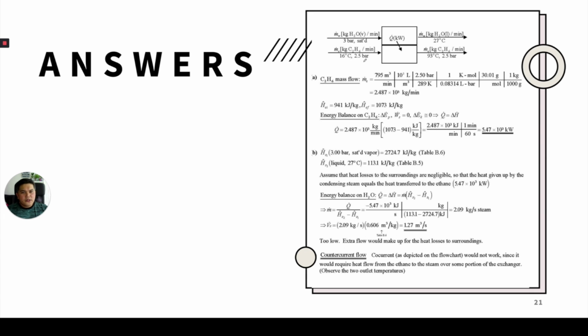So let's look at the solutions, right? So when we have actually the heat exchanger, okay, what I'm trying to do is trying to label this in a simplified way, where you see that, okay, there is water, steam is coming from this side and steam is leaving to this side, okay, and then you know that there is no exchange of mass. Okay, there is no exchange of mass, but again, this is still an open system because there is something coming in and something going out, except that there is no exchange of water to this particular stream. It's just exchange of heat.